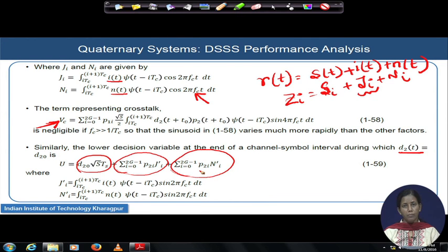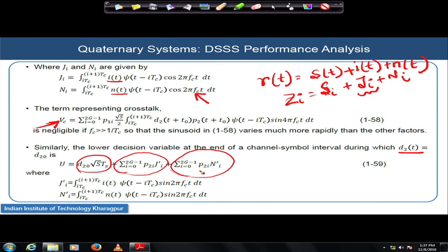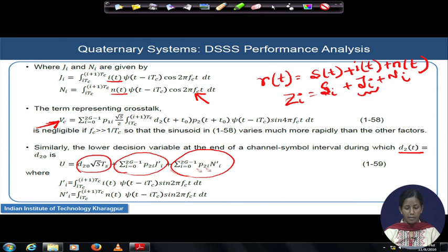So, the contributions from the jamming and the noise power can be equivalently treated in a way that if I know the contribution and the expression over the one path, that will be simply replicated over the next, the contribution from the combined effect of the jamming plus the noise. And this J1 dash and N1 dash, that is Ni dash, have some resemblance; the expressions are basically the same that we have written for the upper path, Ji and Ni. So, there is no difference between these two: the same interfering signal is interfering on both paths, and the same noise signal is getting applied on both paths.